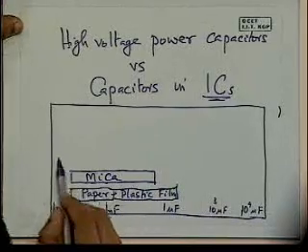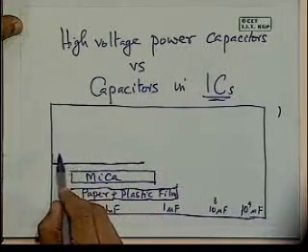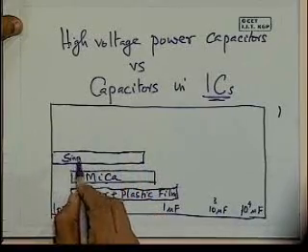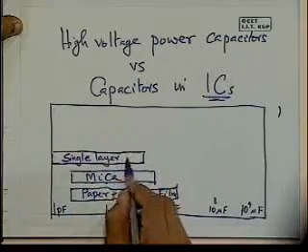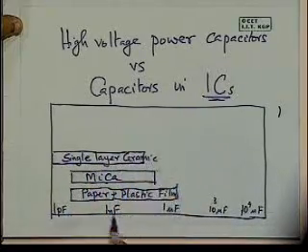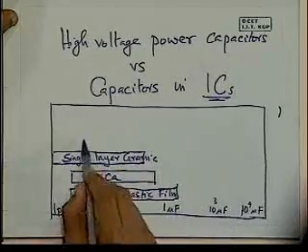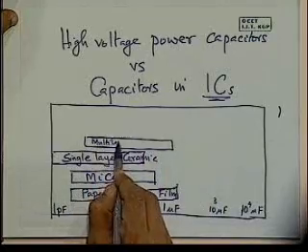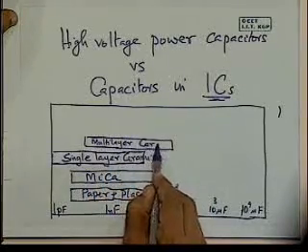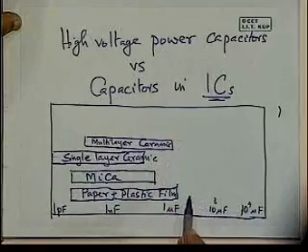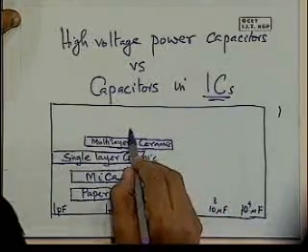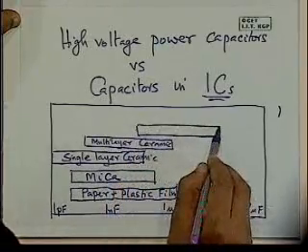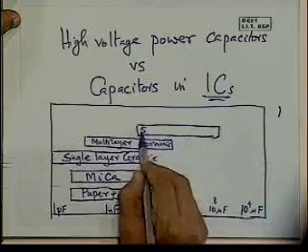And then there are ceramics that can be used, single layer ceramics. We'll see what the definitions and ideas involved here are between single layer and multi-layer and so on. Single layered ceramic capacitors will be of a more limited range. Multi-layer allows us to extend it a little further. Again, ceramic capacitors, but multi-layer capacitors. If you want even higher capacitances, then what we have to do is to go in for the electrolytic capacitors. This is the solid electrolyte.